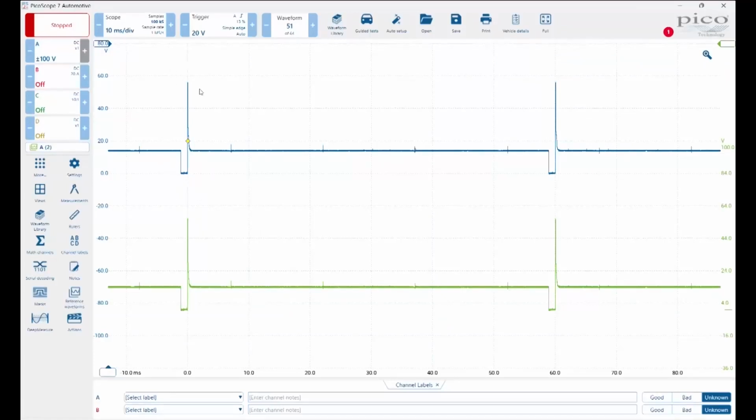Back to the demonstration Phil's going to do on the coil and plug probe, you will see that he uses reference waveforms when we're looking at multiple coil packs together. It's very easy. You can do coil pack number 1, save it as reference waveform, number 2, number 3, and you will notice when there's something different. To be honest, you very quickly build up your own knowledge of what good and bad waveforms look like, particularly with ignition signals, but it's a really nice feature to start to use at the beginning to get used to creating a reference waveform.